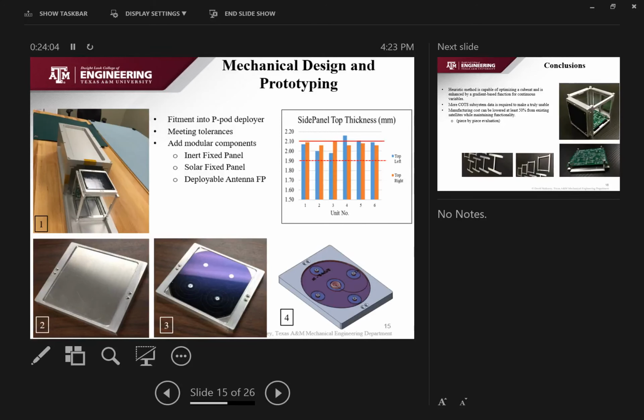And also, I was measuring each part that came off of my CNC to find out if it's meeting the tolerances that I just decided. We're not 100% meeting the tolerances, but you have to keep in mind that I'm changing the process each time to speed it up. So the best tolerance here would likely be a repeatable tolerance once the process is set in stone.